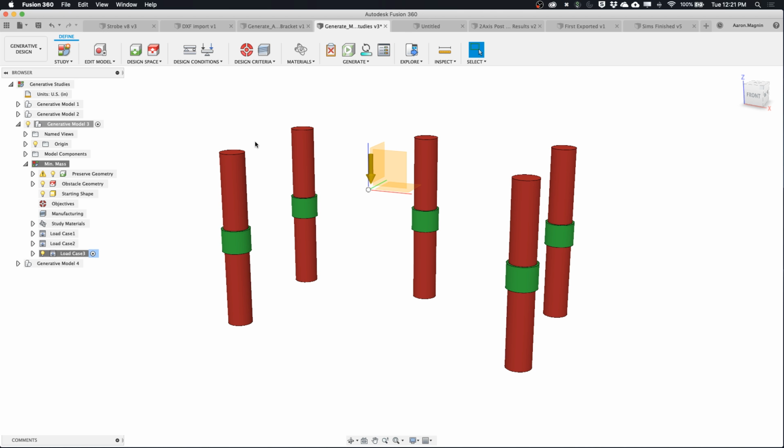This is a pretty flat-looking design space, right? And you might have actually seen this already, but one thing that we did in this release is we added this 2-axis cutting, and this is incredible, just considering how fast we were able to add yet another manufacturing constraint for this generative design technology. 2-axis cutting is going to enable us, or anyone with a water jet, a laser, or plasma, to begin to start to use this generative information in these generative design studies to really optimize those things, lightweight your designs, and cut the amount of material used for any one of these things.